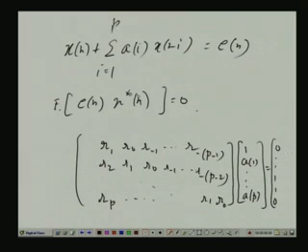Whether it is linear prediction or AR modeling, in the case of linear prediction, say, what is x n? X n is x cap n plus E n. What is x cap n? It is the orthogonal projection or rather prediction of x n from the past p values. This x cap n is nothing but a linear combination of x n minus 1 up to x n minus p, and the error is E n, the summation of the two is x n.